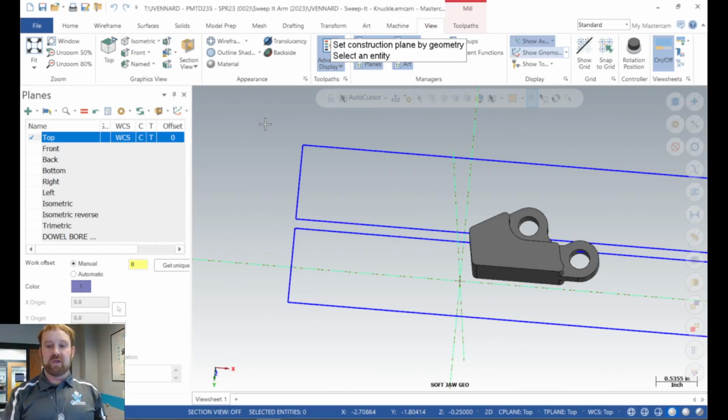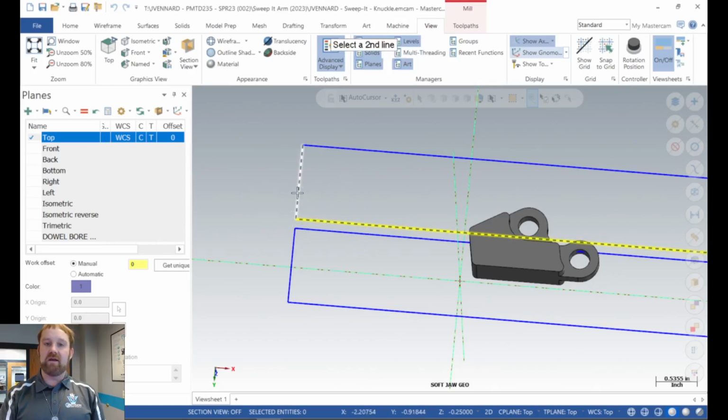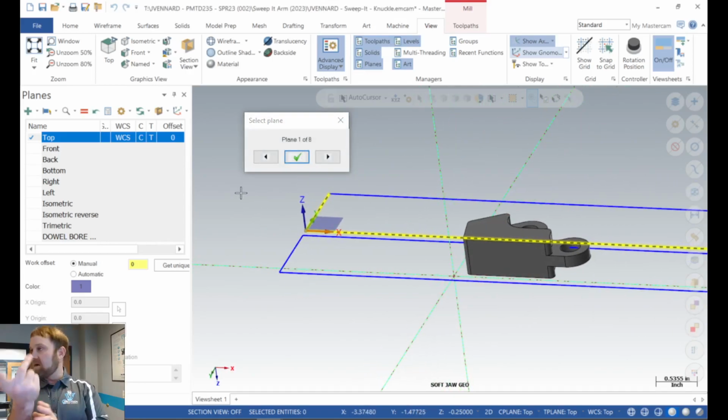or have to go in and edit the spin circle to do it. So like right here, I want this to be my X axis, and this is going to be my Y right here. And then you notice it defaults to the orientation I want. Always be thinking of that right hand rule. That's the orientation I want. My Z's going up, my Y's going away from me, my X is going to the left or the right. I'll tell it okay.